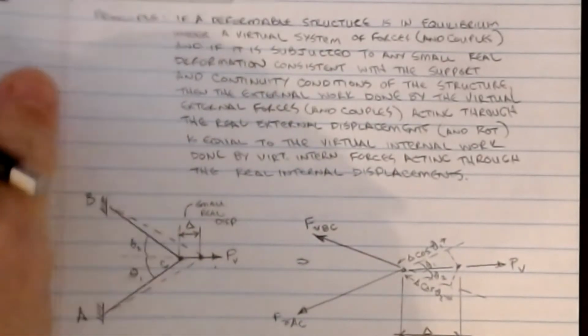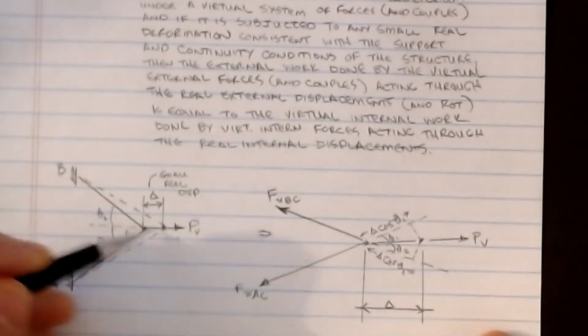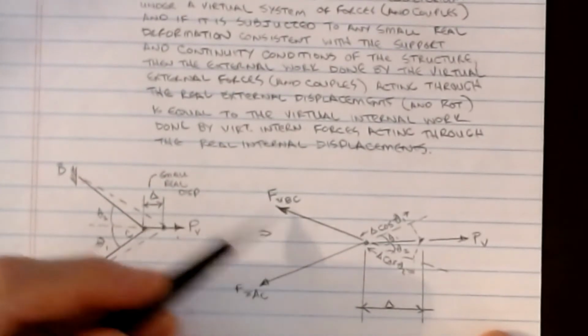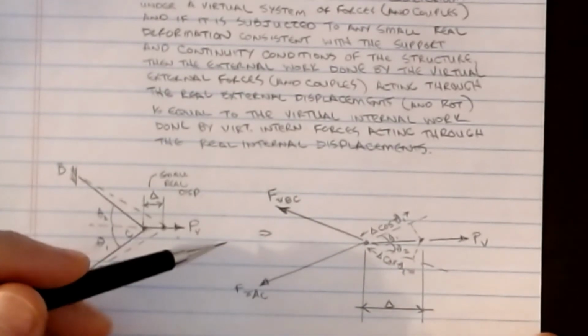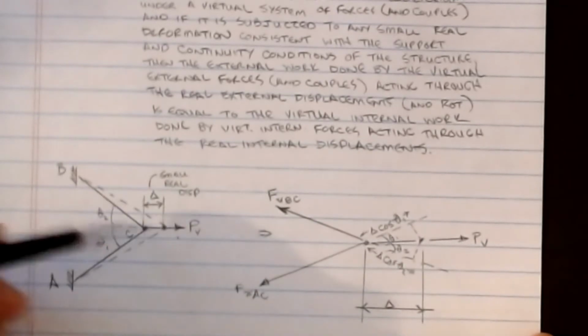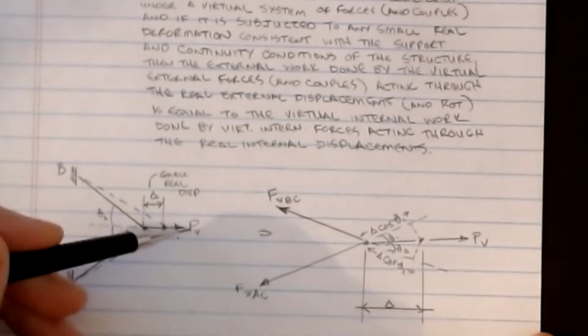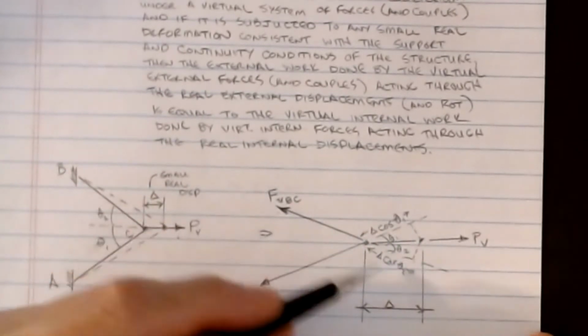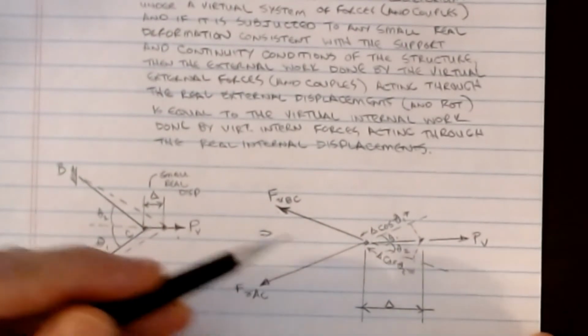Now, what happens is that the forces in these objects become a function of their displacements. In fact, for this guy, that's exactly what we're seeing. We can come up with a little bit of math to figure out the force in member BC, due to this virtual load force F here, it would be this guy. It's a function of the angles, the thetas that we've created.